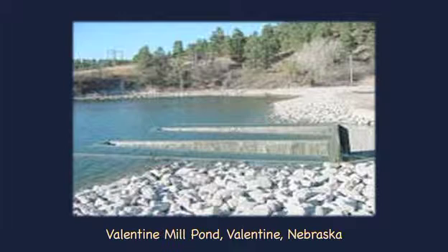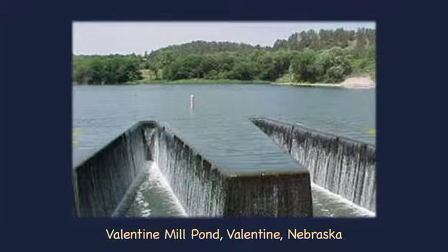Efforts to increase weir discharge while keeping the head constant have led to the concept of labyrinth spillway. A labyrinth spillway increases the effective length of the spillway without actually taking any more physical length, as shown in this example. In practice, the labyrinth spillway works for a limited range of heads. For very large heads, the labyrinth becomes submerged, and the effective length of the spillway reverts back to the original length.